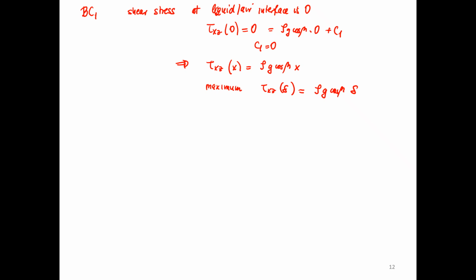This is a very common physical insight. In terms of absolute values, my shear stresses are maximized on solid surfaces, and they're minimized where the velocity is maximum, sometimes in the middle of the profile, or here where I have an open surface to the air, they're minimized at the interface with air. If I did not have contact with air, they would be minimized somewhere in the middle, like in parallel plates, where the velocity is maximum. That's how shear stresses always work.